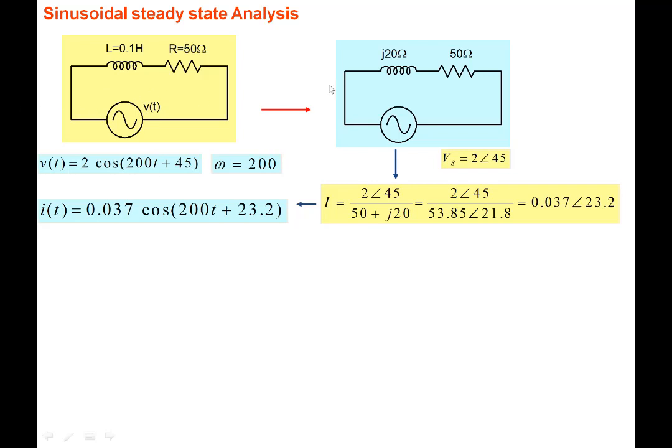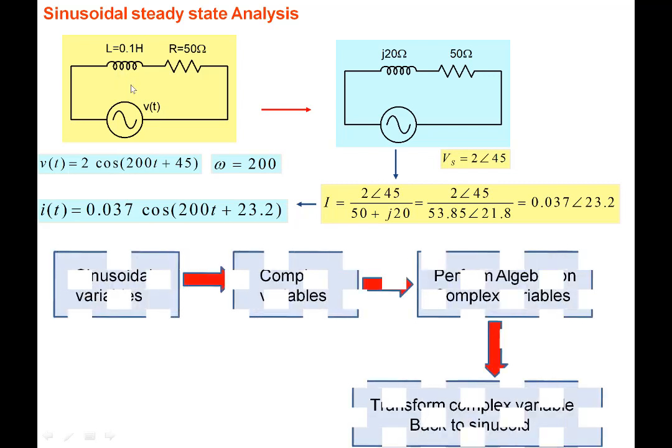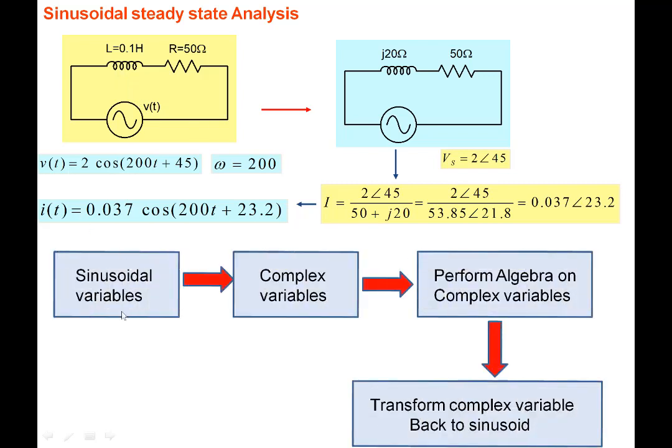When we do a sinusoidal analysis, as electrical engineers, we use phasors to help us calculate the voltages and currents. But if you look at it, directly adding, subtracting, and multiplying sinusoidal variables is a bit difficult. What we are doing is converting into complex variables, performing algebra in the complex domain, and then after we are done, we transform it back to the sinusoid.